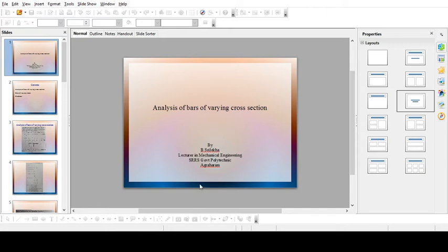So the change in length or extension is 0.7644 equal to sigma 1, that is 63 point something, into 2000 minus L, plus 84.92 into L, by 2 into 10 to the power of 5. If you substitute all the values, you will get L, one positive and one negative, and the positive value you have to consider, that is nothing but 1202. So 1202 mm is the length of bore you are going to make.